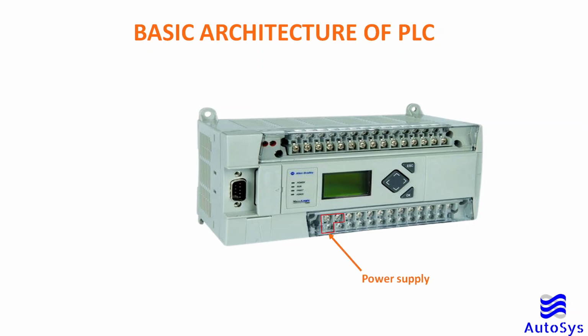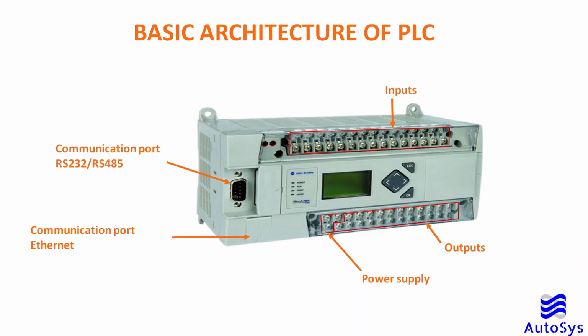So here is the power supply module. You can connect a 230 volt AC or 24 volt DC power supply. This is the output module. Output devices are connected to the output module. Now this is the input module or input card where the input devices are connected. Now this is a communication port which can support RS-232 or RS-485 communication. There is one more communication port for Ethernet and one more communication port for DF1 full duplex Modbus.